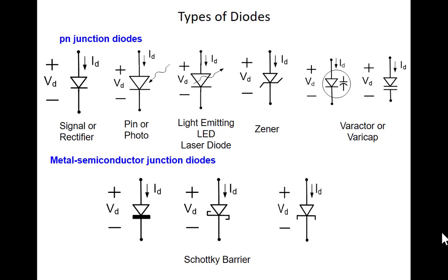Now, on most diodes, you put your PN junction in an opaque case, so light doesn't get into the diode. But if you put your diode in a transparent or translucent case, light can get into the junction. And if you look at a silicon wafer, it looks like silicon is opaque, doesn't it? But actually, at least at some wavelengths of light, silicon is not opaque. So it's easy to get light to flow into the junction if you don't enclose it in a case that keeps light out. When the light or those photons get into that depletion region, they cause current to flow.